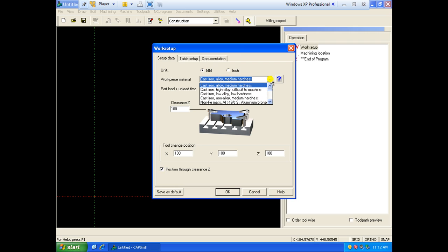This is about the workpiece material, which material we are selecting or practically performing the operation on. It is completely related to the industries, what kind of material they are machining. That is important in practical industries. Presently it is used for lab purposes, so we just need to know about this. You need to learn this. This is the material to be machined, and you need to select that. For our purpose, let it be default; we can select cast and medium hardness.